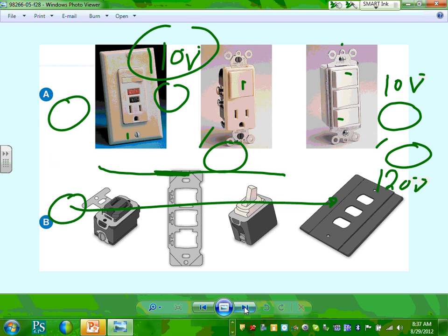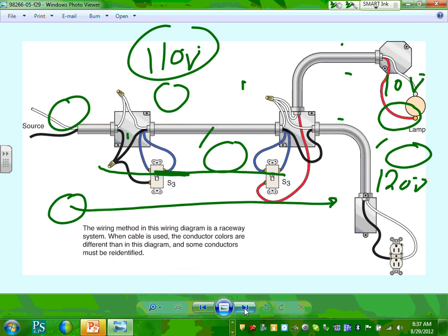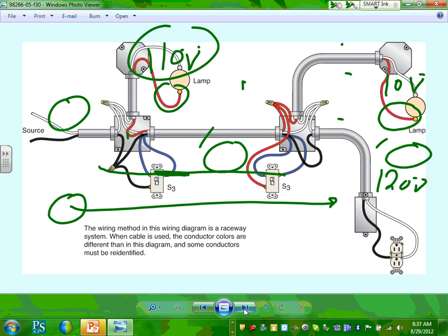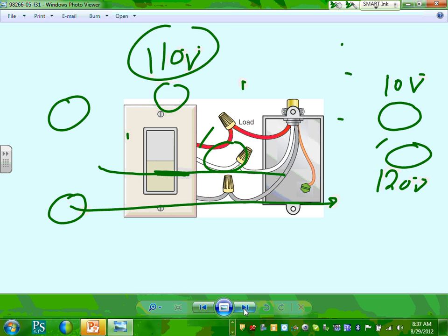We talked about, guys, different types of configuration. You can have three-way switches. You can have all this configuration, a switch with a GFCI. I call this a screw-up, typically. If you put your gang boxes right, you don't want to do that, but it could also be a better way of wiring too. Wiring with conduits, this talks about bonding the ground, guys. You have to bond the metallic boxes right here with your equipment grounding conductor.